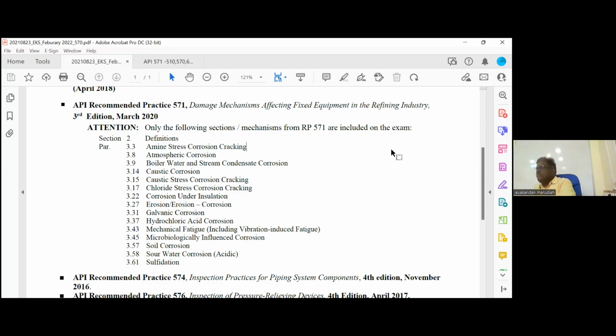Now, what is ACFM? ACFM is alternating current field measurement. It is similar to MPI. You should know ACFM, eddy current, and then acoustic emission testing, because of some damage mechanisms. I will explain briefly, not very deep. It is similar to MPI, but in MPI we are measuring the magnetic flux leakage. Here we are actually measuring the current.